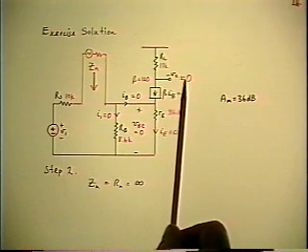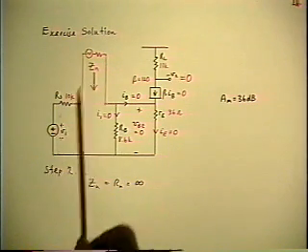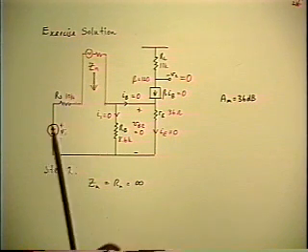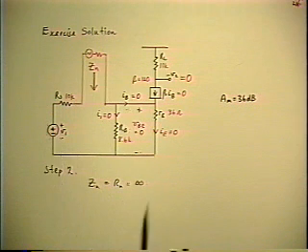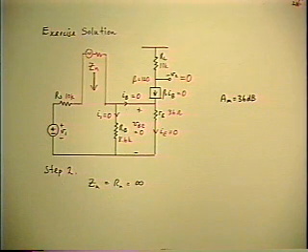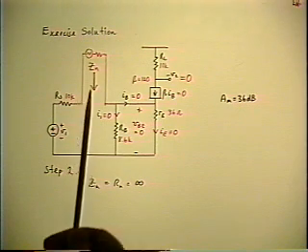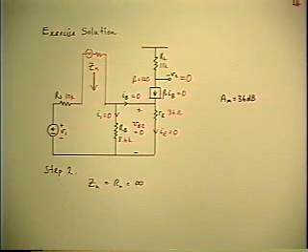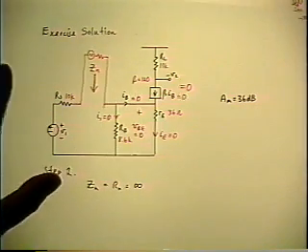The only way you can get a null at the output is to have those two sources cancel each other directly, equal and opposite. That's the adjustment that you need to get the null. So if the two sources cancel directly, there's 0 current everywhere. That's a special case because the two sources happen to be directly in series. So now we have both the RD and the Rn.